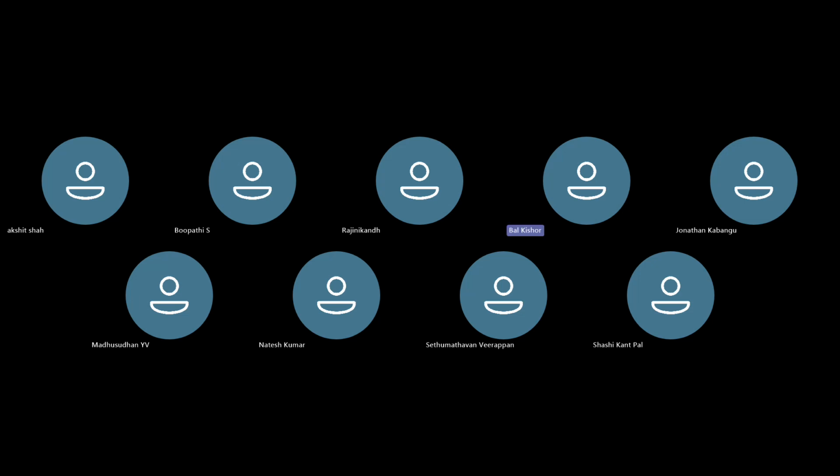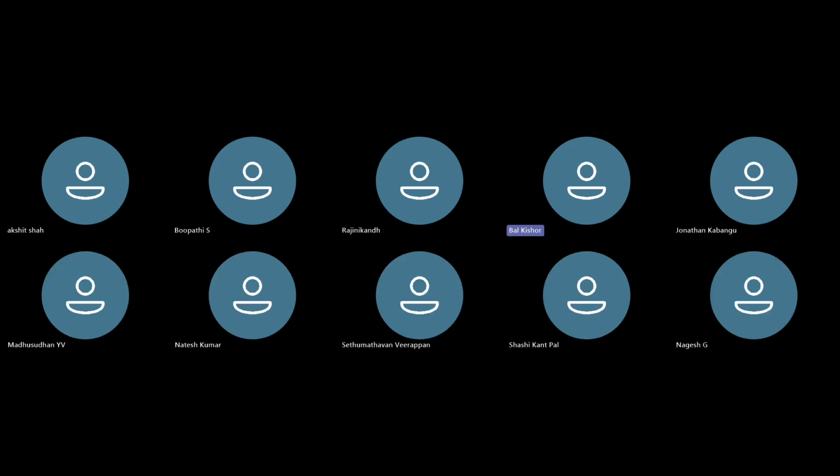Now let us quickly move to the remaining portion of LTspice that we had. I hope you are clear about the sources up to PLL sources, or any other sources that were there, right? If you are not clear, let me quickly make one circuit: V for voltage, then if we press D, that will take a diode, and let's put a resistor, and then G for ground.